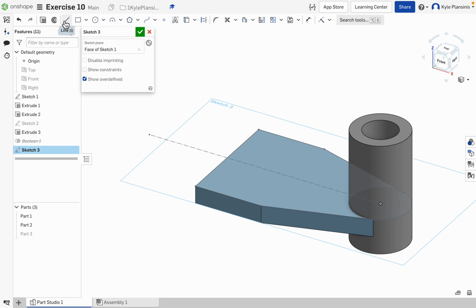So I want to use Sketch, select that surface, offset, and if I select that surface again, you can see that it's making a shape the exact same as the outside edge of that surface. I can use this to go bigger or smaller. For this one, we're going 0.625 inward. Make sure you drag it inward before you put that measurement in.